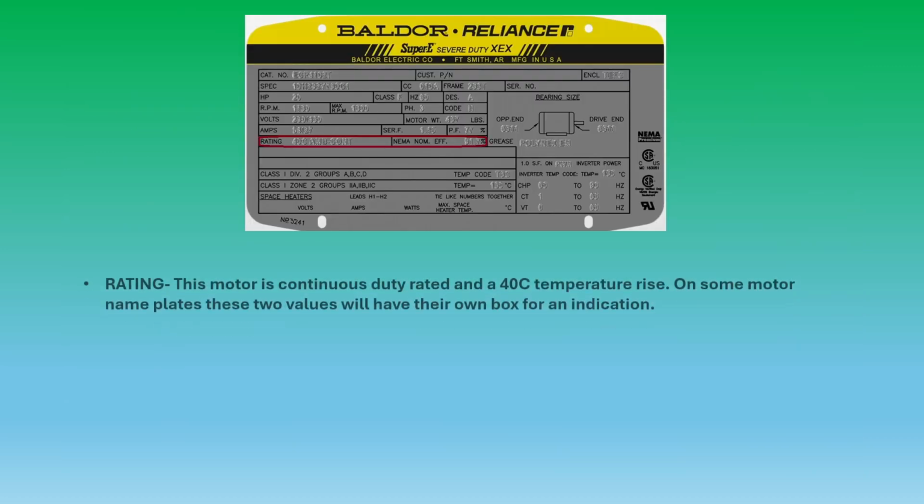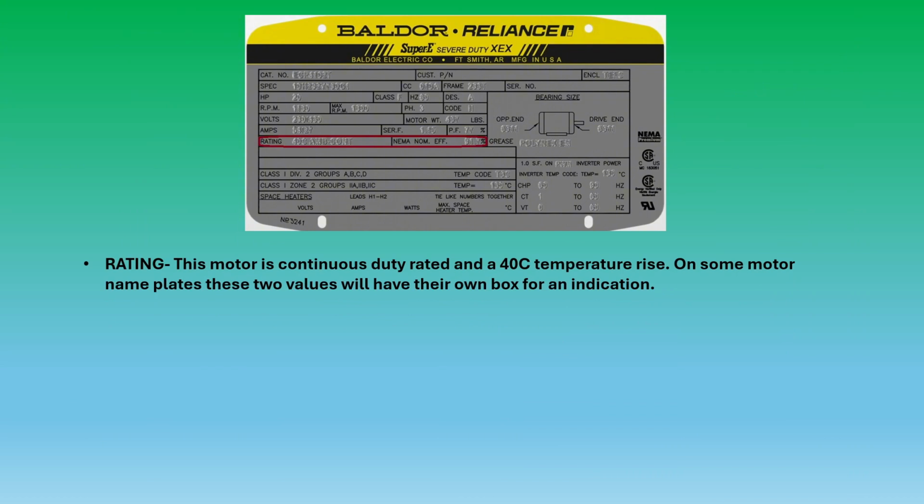Next, we have rating. In this particular case, this motor is continuous duty rated and a 40 degrees C temperature rise. On some motor nameplates, these two values will have their own box for indication. Continuous, of course, continuous duty in the code, anything running 3 hours or more within a 24-hour period.